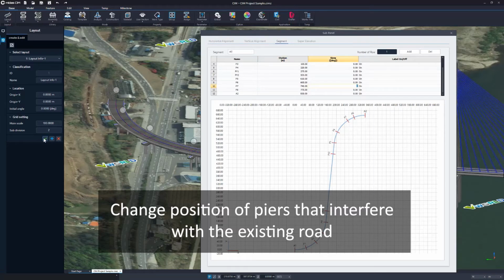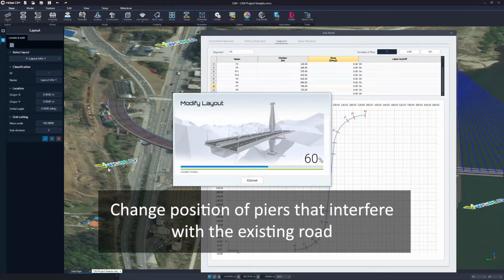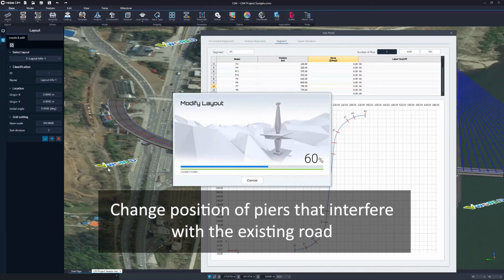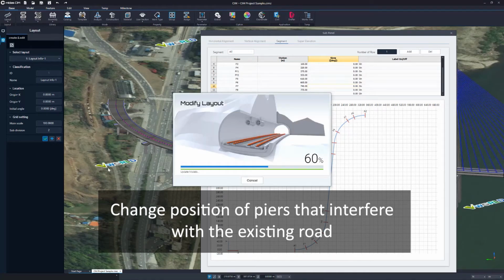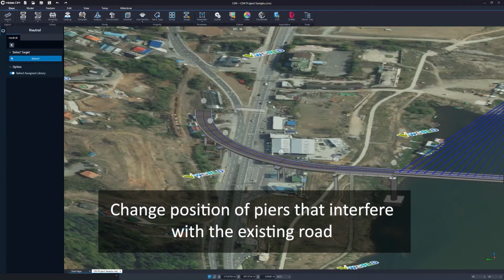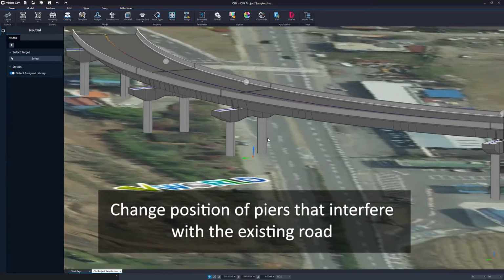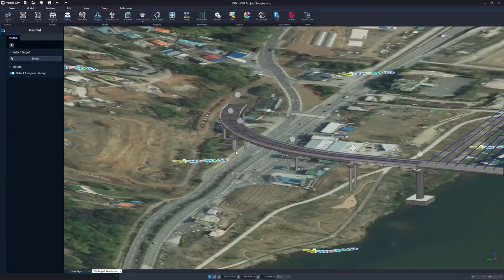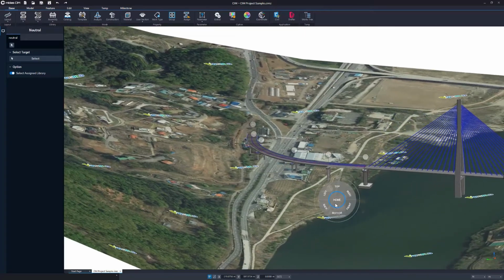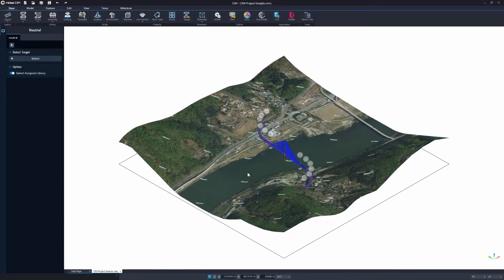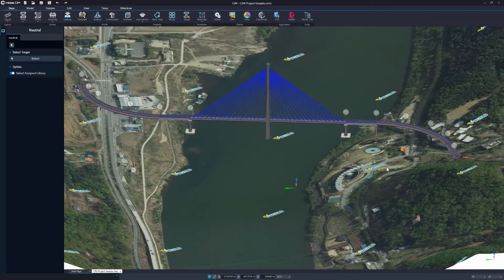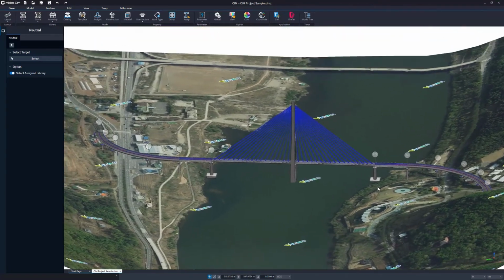The position of the pier can be changed by modifying the segment position of the alignment. Since the pier library is linked to the alignment, moving the segment coordinates of this alignment automatically moves the point library unit pier. The substructure, which is a curb library unit, will automatically extend or shrink as the alignment changes.